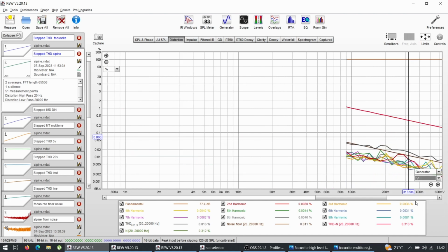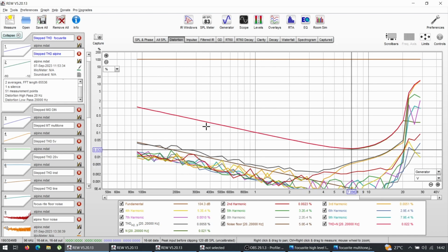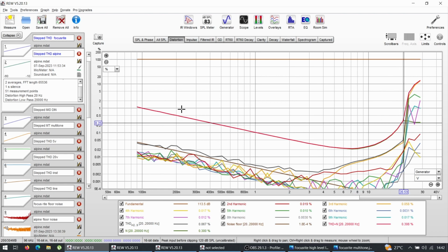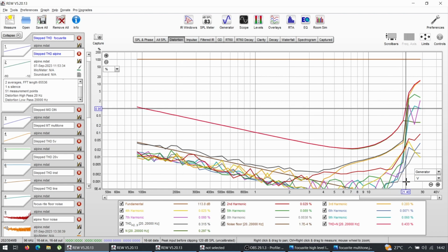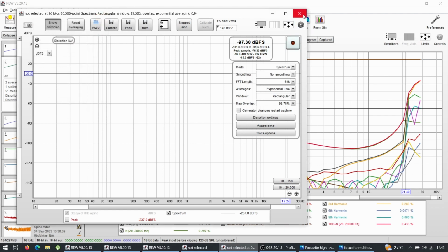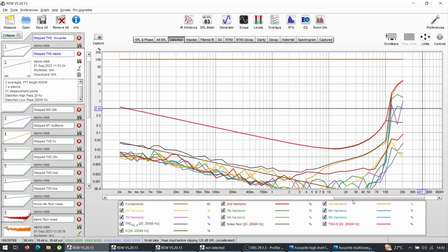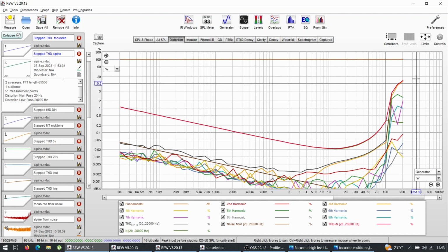So we can choose the voltage, which shows me the calibrated voltage. So we can see that this amplifier performs best with the lowest possible THD at about 7 volts. And then 1% THD is 21 volts. So again, 21 volts, if you use Ohm's law, you can calculate the wattage. However, if you remember in RTA, when we enter the ohm value, we can choose the scale in wattage, and it shows me the actual watts. Now it's not 100% accurate because of 4.1, 4.2 ohms and voltage and so on. So it's not an amp dyno, but it gives you a good indication how the amp performs.